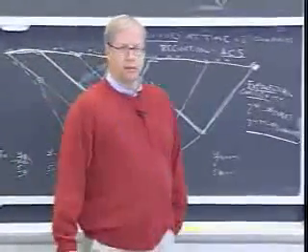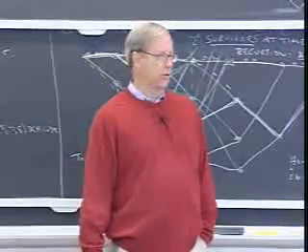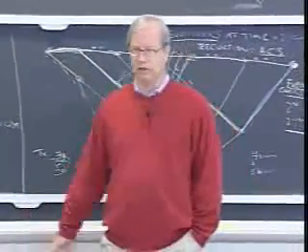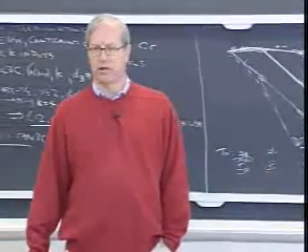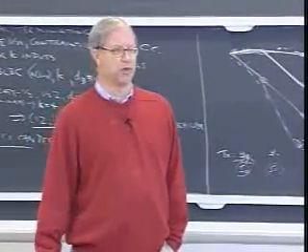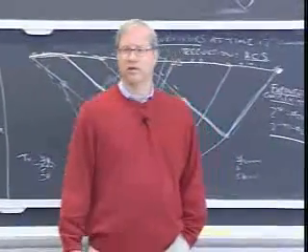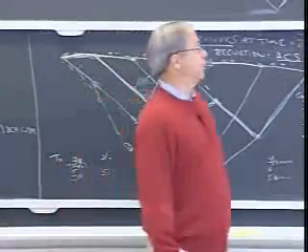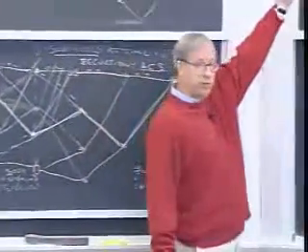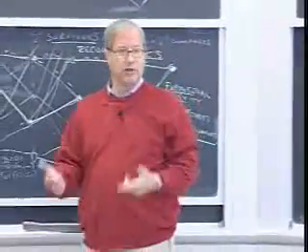For block codes, we had nice algebraic ways of doing this, roots of polynomials, Reed-Solomon codes. We could develop an algebraic formula which told us what the minimum distance was. Do we have any nice algebraic constructions like that for convolutional codes? No. Basically, you've got to search all the possible polynomials where the maximum degree is nu. Take pairs of polynomials.